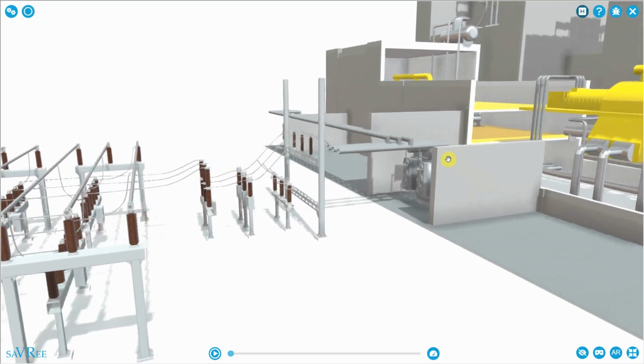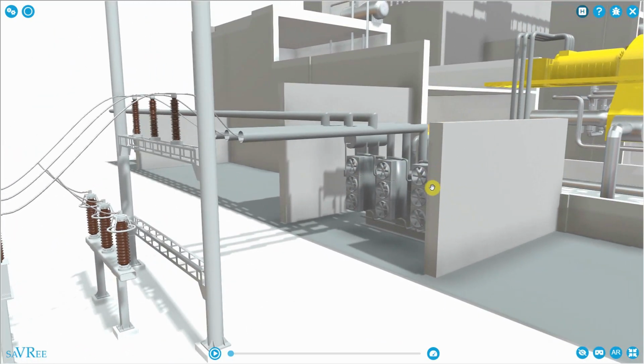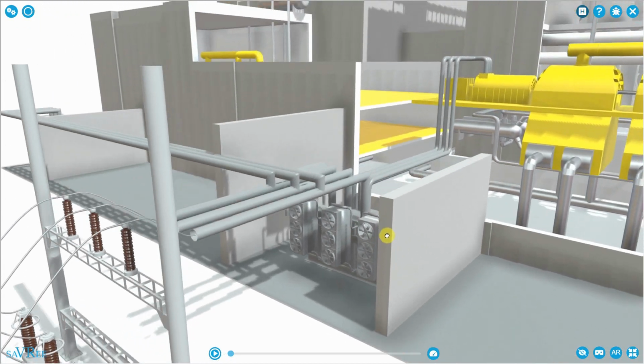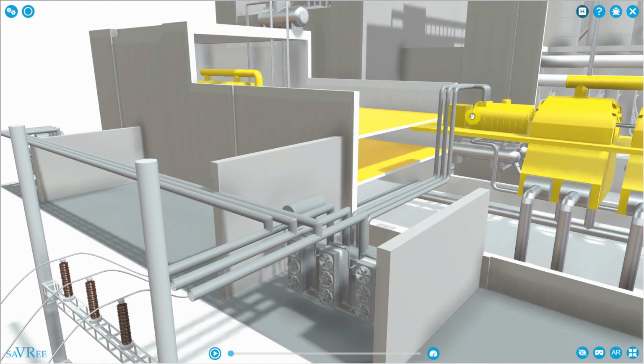It depends upon the transformer and what voltage we wish to achieve. The transformer's purpose is to increase the voltage from 10,000 or 20,000 volts from the generator up to 110,000 or 220,000 volts, etc. Because we're increasing the voltage, we call this a step-up transformer or a generator step-up transformer, GSU for short.